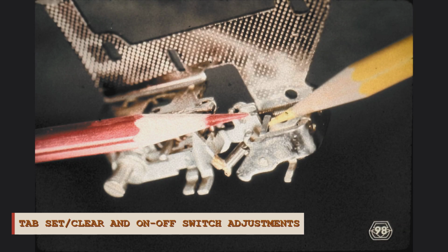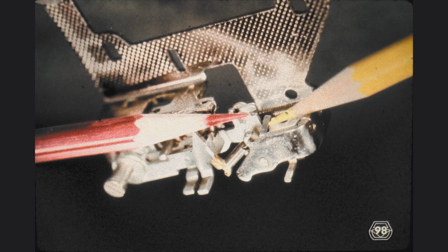You will remember that on the new style tabulation lever, the J-shaped cutout, indicated by the red pencil, also provides an overthrow stop for the tabulation lever. The length of the tab torque bar link, which connects the intermediate tab crank to the tab torque bar, must be adjusted so that the torque bar has the ability to rotate the tabulation lever, at the red pencil, 1/4 of 1 millimeter beyond the latch-up point for the tabulation lever, at the yellow pencil.